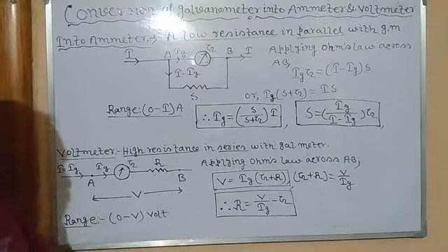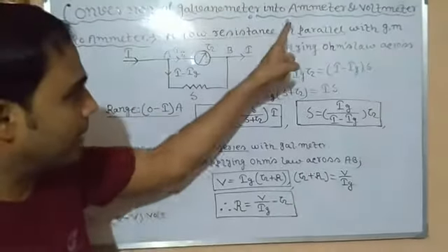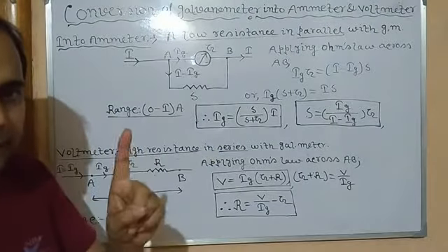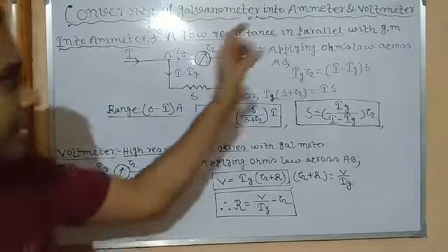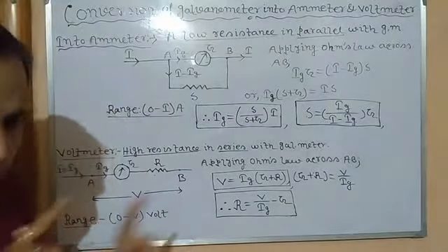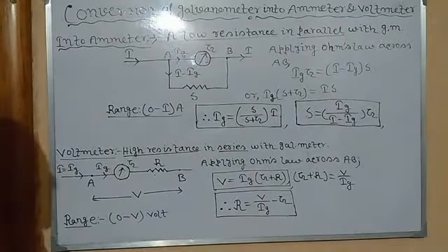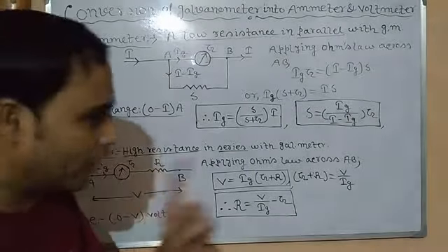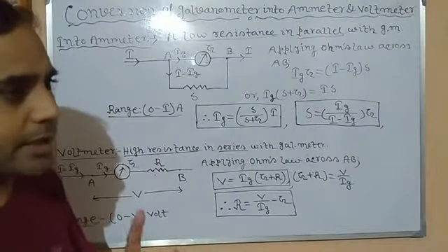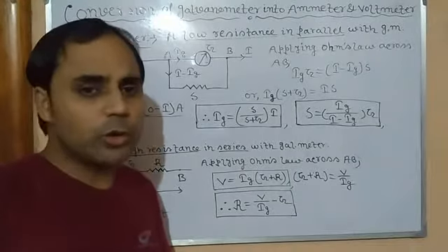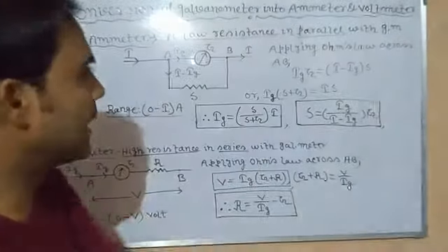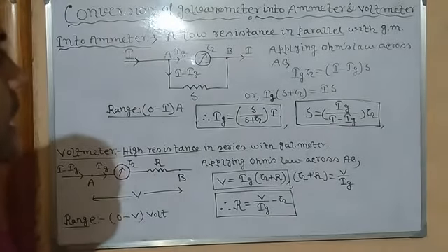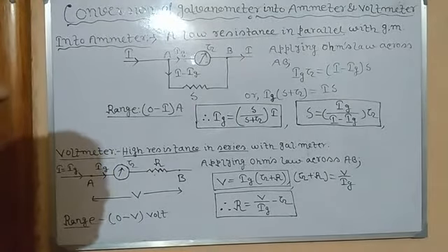You have to remember this through a short trick. Since the function of the ammeter is to measure the current of the circuit, the entire current through the circuit should pass through it, so its resistance should be zero or negligible. In case of the voltmeter, its function is not to measure the current, only the voltage. It means it doesn't allow current through it. When the resistance is high, we all know that resistance means resisting the current. So we can say the voltmeter is an instrument with high resistance compared to other instruments, and it is connected in parallel. Clear?